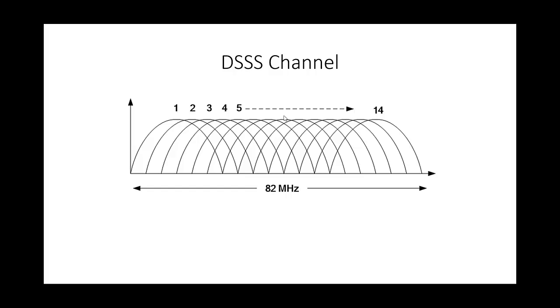Because there is much more redundant information than actual signal, the entire transmission appears to be random noise, making it much harder to detect as meaningful signal. This means that it is harder to intercept communications, and it's for this reason DSSS has been used in military communications. Some of the extra information also acts as a checksum on the original signal, allowing it to be reconstructed if some of it is damaged by interference from other sources.